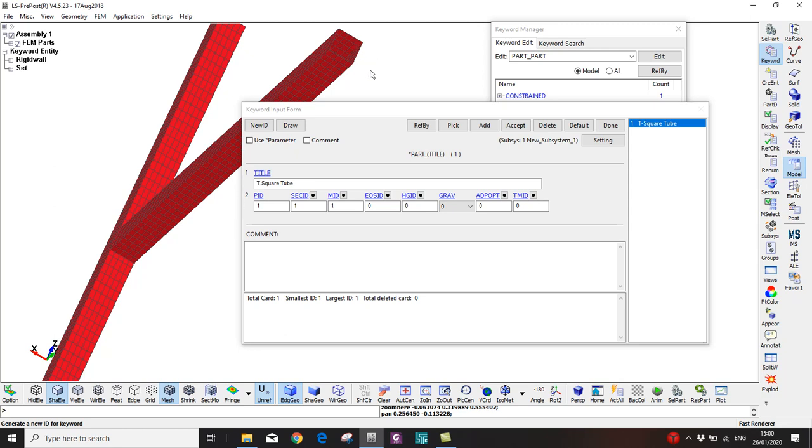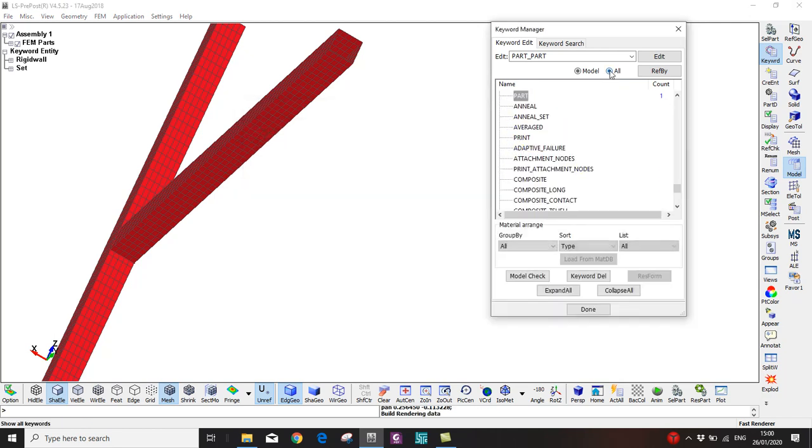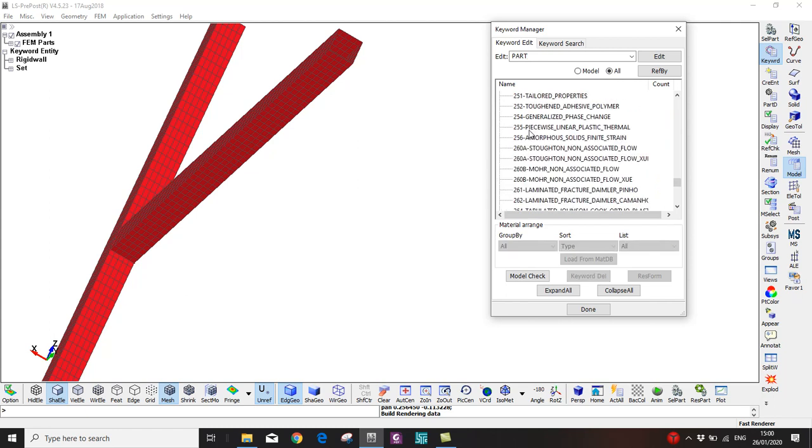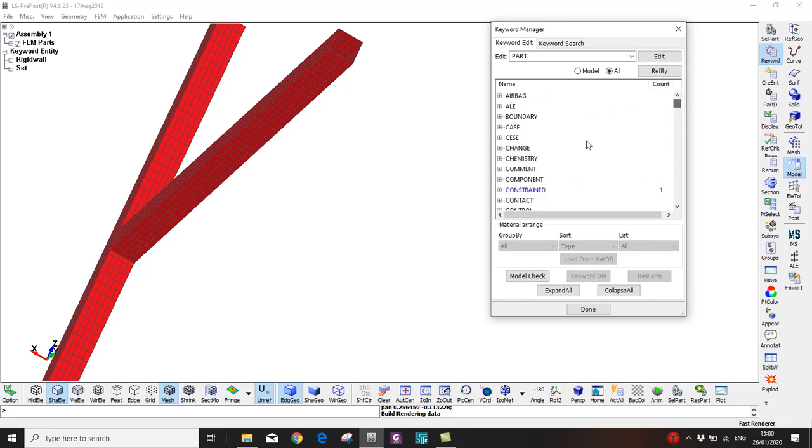But if we were to use a solid model with a Johnson-Cook material, it will not work like this. We need to define one more thing, which we call the equation of state. Let's go up here, equation of state, EOS, and we use the linear polynomial.